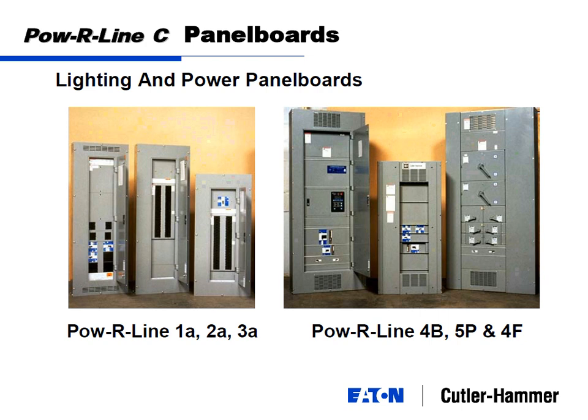Resettable. If you get a fault, whether you're a contractor trying to install this and some wire was running and it keeps tripping on you, you just keep having to reset it to finally track down your fault, and then you're good to go and you can walk away. You got a fusible switch in there and you get a fault or maybe a couple faults while you're starting up. Every time you get a fault, you got to say, oh, $50 replacement fuses, $50 replacement fuses.